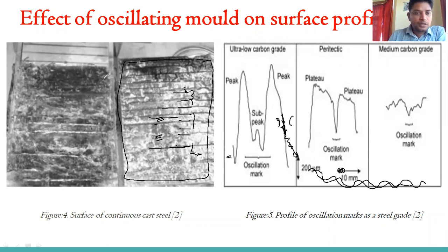But if you look at the solidifying shell surface, the inside of this shell surface, it looks somewhat black. It is not clean. There is a possibility that this is because sometimes there is no proper lubrication, so the molten material itself covers the surface, and also we are using high temperatures.